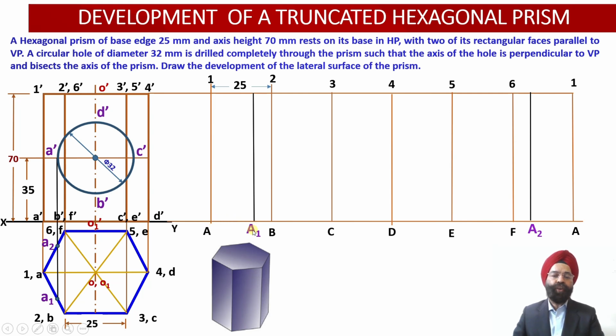So corresponding to point A1, a vertical black color generator we have added over here, so that onto this vertical generator emerging through the point A1, point A will be located onto the front face of this hexagonal prism corresponding to the circular hole that we are going to obtain in the front face of the solid.